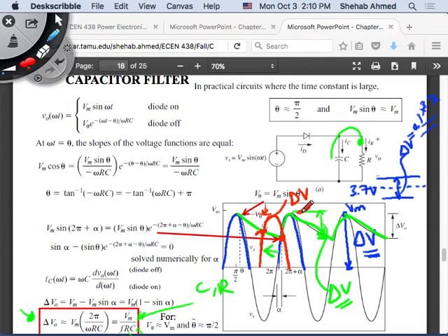Of course, the other thing is these devices have lower losses. That makes sense, because you're switching a lot faster. When you switch a lot faster, you're more prone to switching losses, right? If you have high switching losses, then you cannot tolerate that. The temperature will go high, and you will burn your device. But these devices have a big advantage: you can switch them very fast, which allows you to use smaller L's and smaller C's, and they will survive at that temperature. Their switching losses are very low, and they can survive at higher temperatures as well. So they have lots of benefits from a device physics perspective.